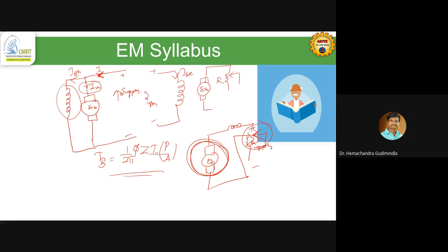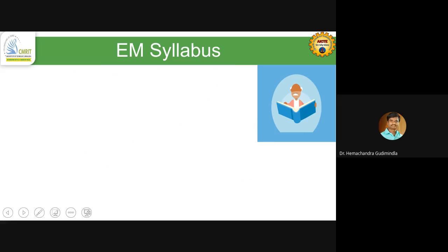Instead of that, plugging. What is meant by plugging? Same thing, but the resistance we are adding to the armature directly in series. In dynamic braking we are adding the resistance in parallel. Now plugging means we are adding the resistance in series with the armature coil.